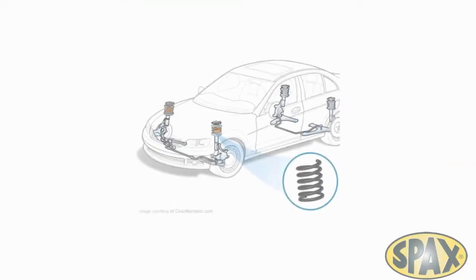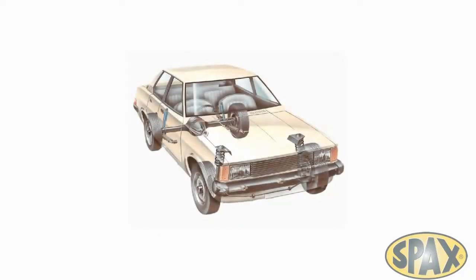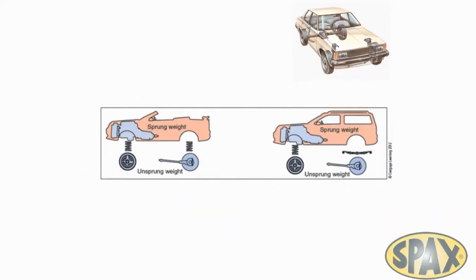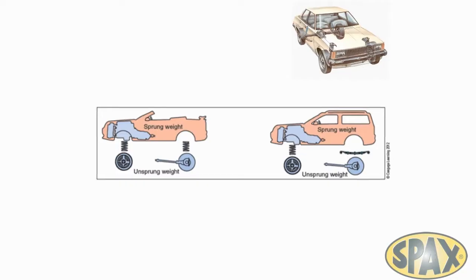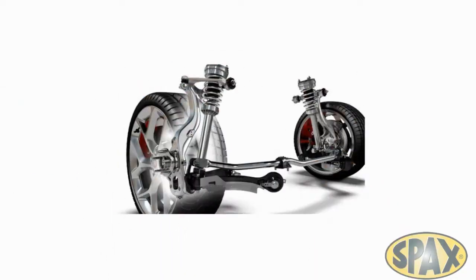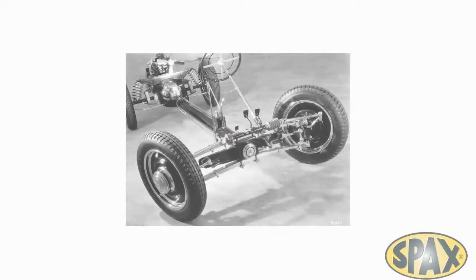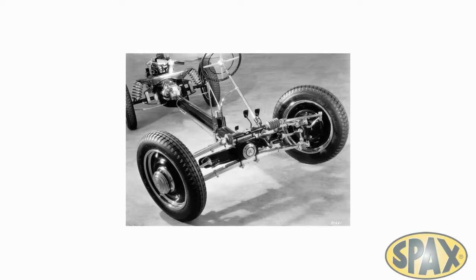Springs are simple and essential devices. They're designed to support the mass of the vehicle, including the engine, body, chassis, gearbox, interior, passengers and goods. The weight carried is known as the sprung weight. Designers strive to minimise the unsprung weight of a car. That's the wheels, tyres, axles and lower suspension components. This is done so that the suspension system overall can minimise the necessity to compensate for those parts and give the majority of their attention to the sprung mass.